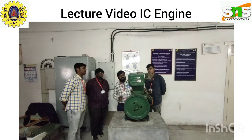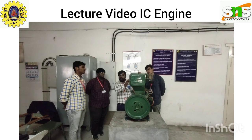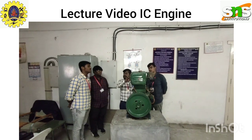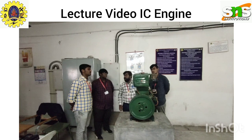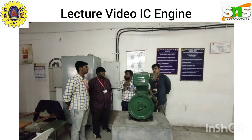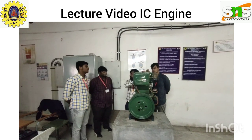The top of the engine cylinder is the cylinder head. It is also made up of cast iron and aluminium. It consists of water jackets, fuel injector, because this is the diesel engine, so fuel injector, inlet valve, and exhaust valve. Here this is the 4-stroke engine, so we call it a valve. In the 2-stroke engine, we call it a port.